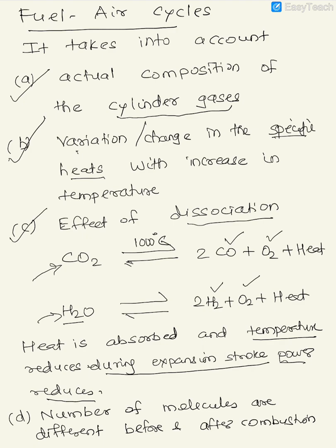Also, in the air standard analysis, we had considered that the number of molecules before and after heat addition remains the same, and that is because we had assumed that the heat is supplied not by any combustion phenomenon but by bringing the source at a high temperature in contact with the working fluid. Here in the fuel air analysis, we consider that there is a change in the number of molecules before and after combustion. So this is the difference between the fuel air cycle analysis and the air standard cycle analysis.